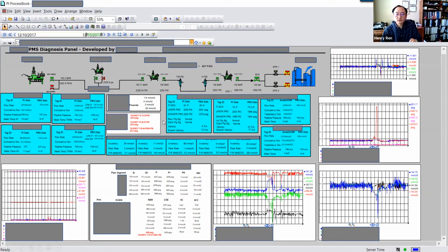So coming down to virtual sensor application, for each tag, which tag you're going to pick, you really have to do a lot of analysis, and you have to run a model and compare. Now over time, you know, okay, this sensor is good, I'm going to rely on it, this sensor is not good, I'm not going to rely on it, I have to use the model values.